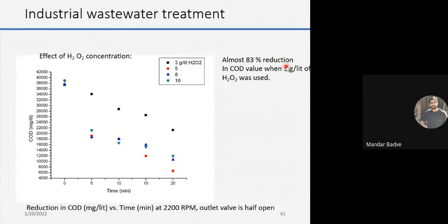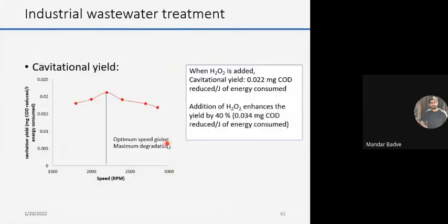At higher concentration, the efficiency slightly reduced, because hydrogen peroxide is highly reactive and sort of has a scavenging effect, and it is very well known. Therefore, it goes down. So it is also necessary to optimize in order to use these oxidants effectively. Okay.